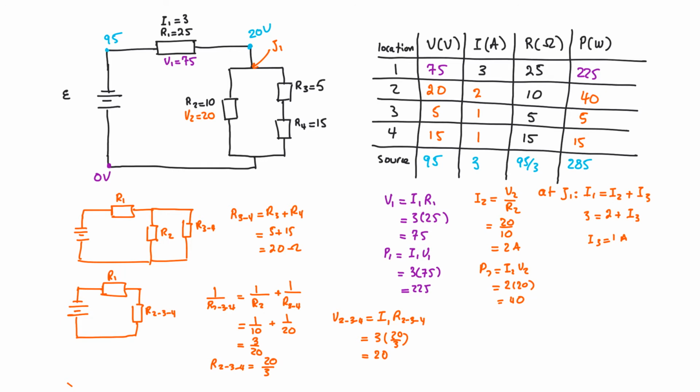In this particular case, we had no idea what the potential difference across here and here were, but we did know how much the potential difference here was. So by combining these, we were able to put these all into one resistance, and knowing that there were 3 amps of current flowing out of the battery source, we were able to figure out what the potential difference across this region was. Once we had that, we could figure out the current here, and using Kirchhoff's current law, we could find the current going here, and therefore the voltage, or potential difference. And once we have that, we could also find the potential difference across the battery. We could have done that earlier as well, but again, there are so many different ways of solving this, and by combining them, it will really simplify our question to a more manageable state.